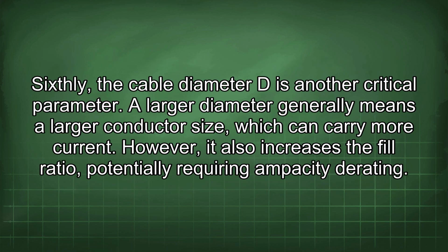Sixthly, the cable diameter D is another critical parameter. A larger diameter generally means a larger conductor size, which can carry more current. However, it also increases the fill ratio, potentially requiring ampacity derating.